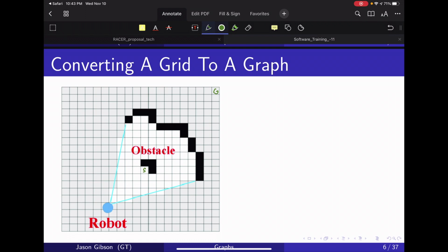to reach. So if I'm starting at this start location, the way I can build a graph is I have my start location, and let's say I can move to this grid cell or this grid cell, and you can do that by creating edges and then creating two new states here that would represent those grid cells. And I can just keep doing this, building it over and over again. What this allows me to represent is how I can transfer from one grid cell to another grid cell.